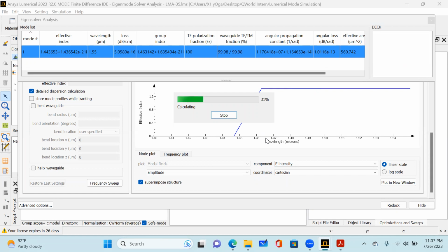There are a lot of tips behind this, because, for example, if you need to analyze behind the core, I will define a very dense mesh in this specific area, not on the whole device. Because we need to efficiently use our computational resources, to get higher accuracy results with the minimum amount of time, right?